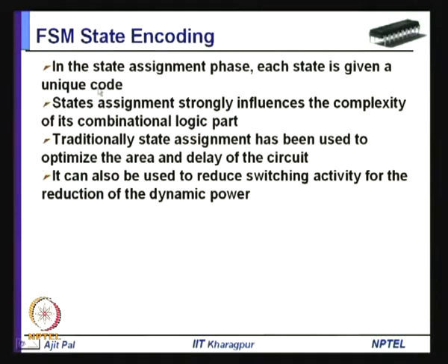Now, since power is one of the most important design parameters, we can use state assignment for reducing the power consumption. In other words, you can use it to reduce switching activity. So, the basic requirement here is to do encoding such that the dynamic power is reduced.